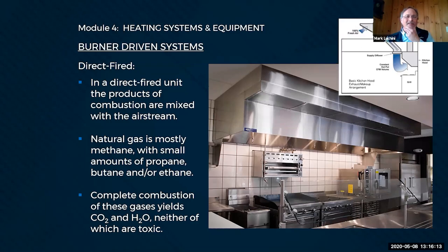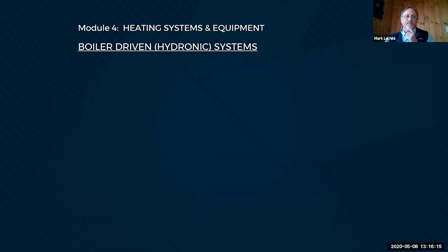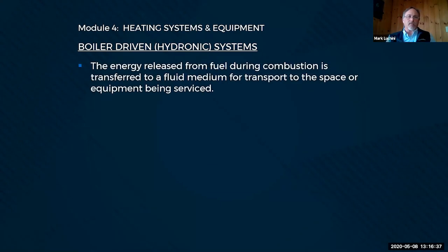All right, moving on. Let's talk about boiler-driven systems. Boiler-driven or hydronic systems. A lot of times when we talk to engineers and they talk about hydronic systems, they're really talking about hot water or chilled water systems. But strictly speaking, hydronic does include steam as well. It's any system that's water-based, and steam systems obviously are water-based. So in a boiler system, the energy released from the fuel is actually transferred to a fluid medium for transport.